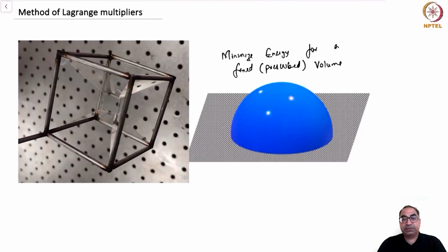In the previous set of lectures, we determined the shape of a static meniscus using two different approaches. One was the force balance approach, and the other was an energy minimization approach. In particular, in the energy minimization approach, we showed that there is a quantity which we can conveniently call the Lagrangian, and this quantity has to satisfy the so-called Euler-Lagrange equations. This quantity Lagrangian, or a function f as we called it, is the sum of the surface energy and the gravitational potential energy.